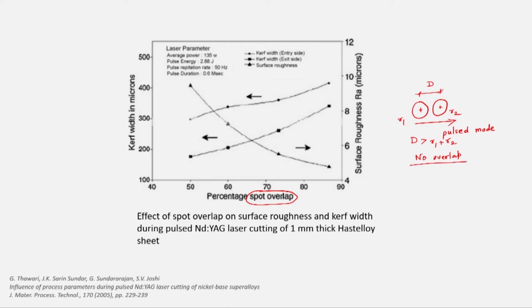But consider that we want a deliberate overlap of the second pulse over the first pulse to get some channel. So, what should be the optimum overlap between pulse 1 and pulse 2? It should not be at the same spot. Here we consider a pulse overlap of about 40% to 90%.